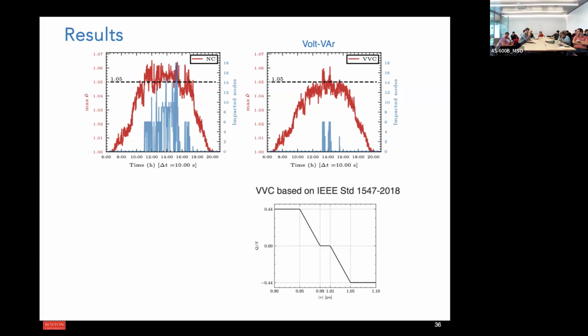But what is happening here is that if you have an overvoltage condition for more than a few seconds, the inverter will shut off to protect itself. So what we implemented here is the following: if after 5 seconds there is still an overvoltage condition, the inverter shuts off, and then you start a timer and try to turn back on after a given deadline. So this is what we get in that case.